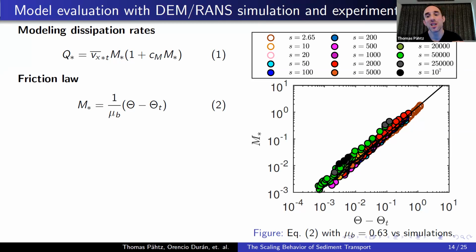This is in a sense the pressure, the particle pressure at the surface. And what we are relating is the particle pressure at the surface to the particle shear stress at the surface, and this involves a friction coefficient μ. And the particle shear stress is, by virtue of momentum conservation, the mixture shear stress, theta, minus the remaining shear stress of the flow at the surface.